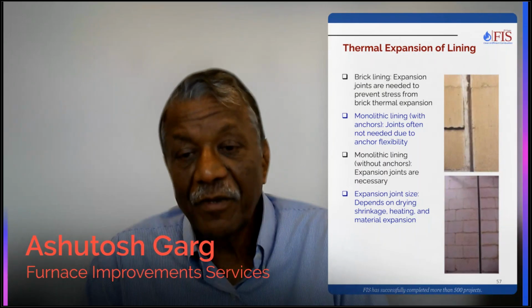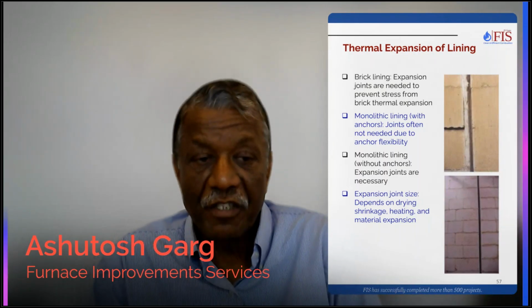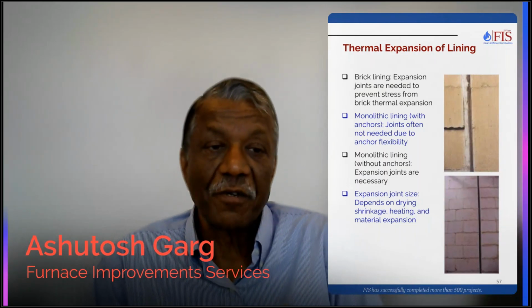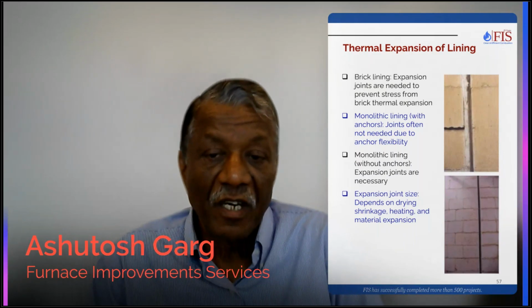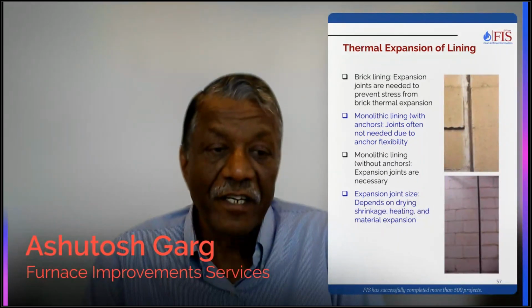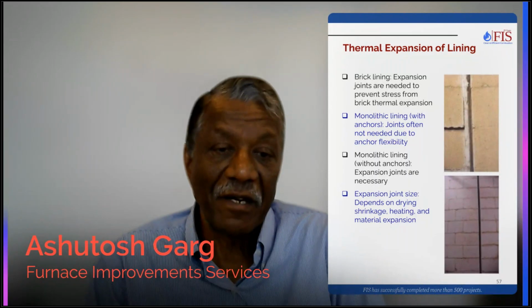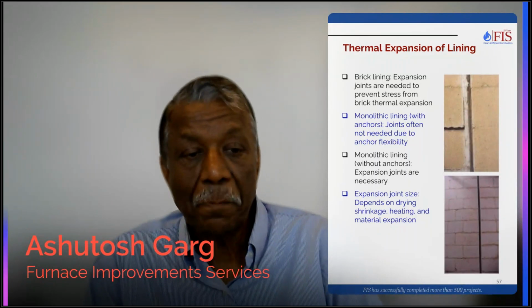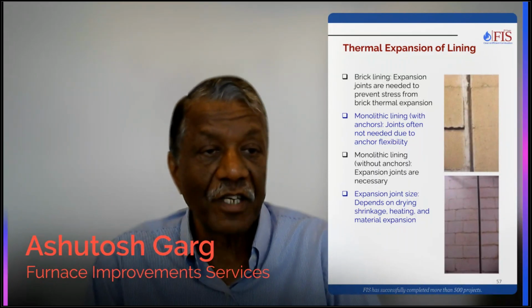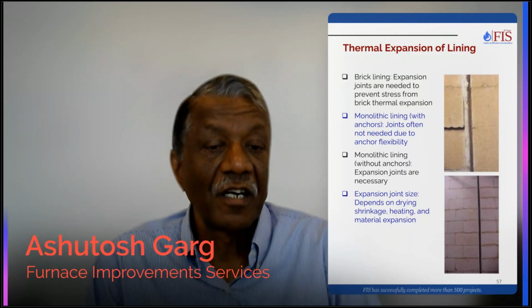In ceramic fiber, that issue is not there, but in most of the bricks, most of the castables, you need to provide expansion joints so that you don't get cracking taking place. This is on the brick lining, this is on the expansion in the castable.